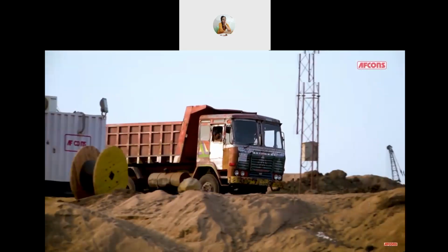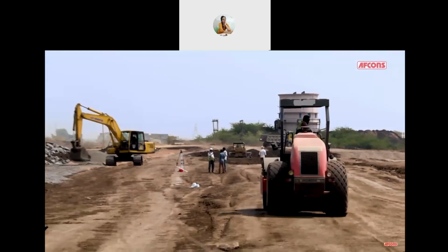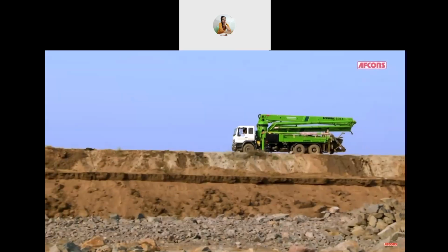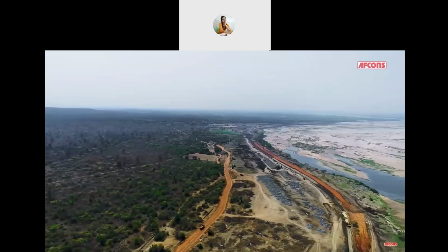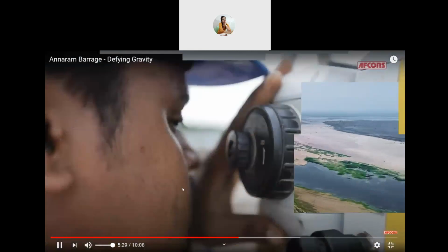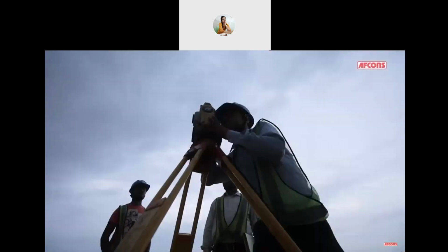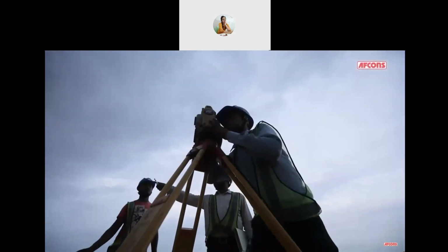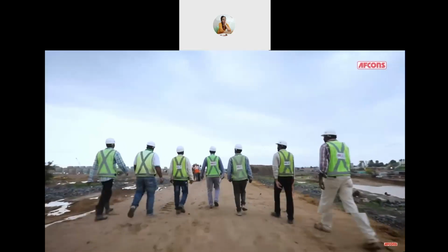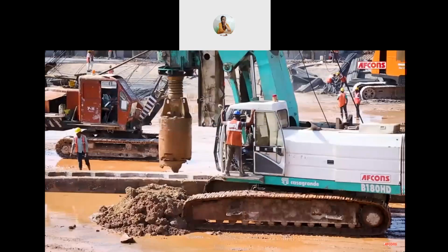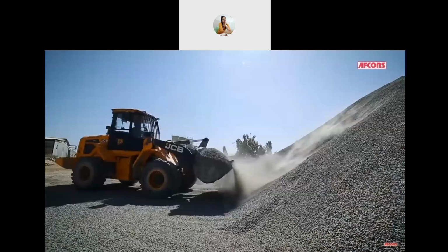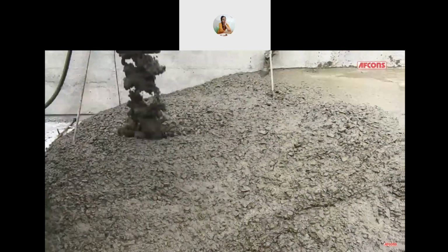At the outset, a change in plan threatened to derail the schedule. The location of the barrage was shifted, which increased the length to 1,270 meters. The change also meant that the geological survey would need to be done at the new site once again. The result was extra work of more than 4,000 piles and a 20% increase over the estimated quantities of concreting and steel.